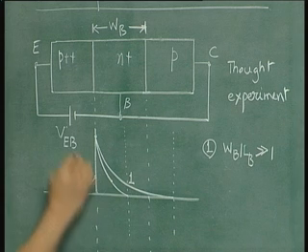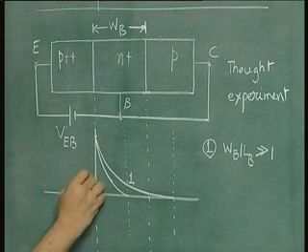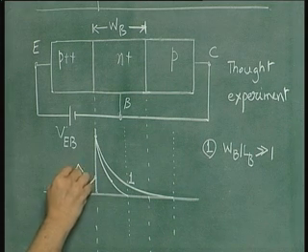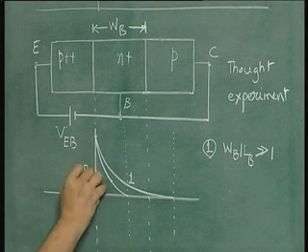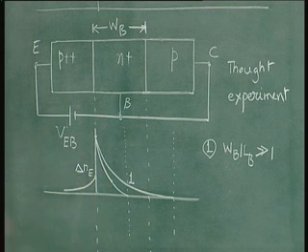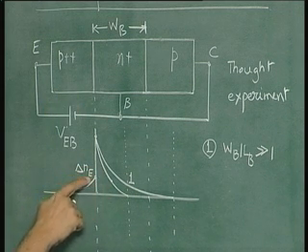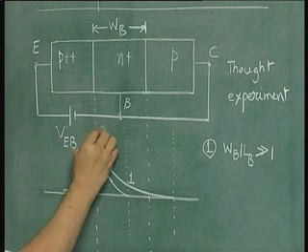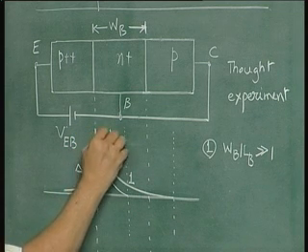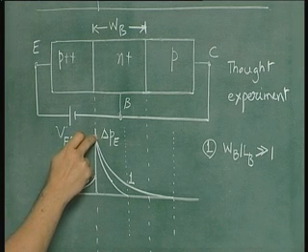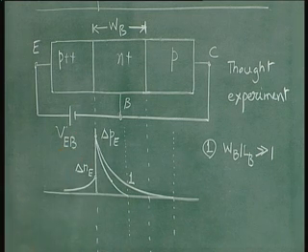The minority carrier concentration is electrons here. So the excess carrier concentration we will indicate as capital delta N suffix E at the emitter junction on the P side boundary. So delta NE is the maximum value of the excess carrier concentration, or the boundary value of the excess carrier concentration of electrons on the P side. Similarly, this we will denote as delta PE. This is the boundary value of the excess hole concentration at the emitter junction on the N side.